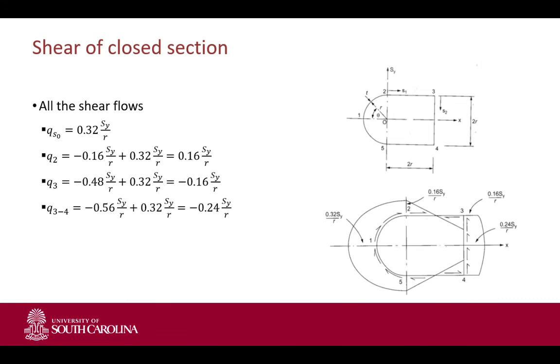And like I said earlier, the negative sign basically indicates the direction of the shear flow. So as you can see here, at one point you basically switch signs or direction of the shear flow. That doesn't represent anything else other than just the directionality. So there's no such thing as a negative shear flow. It's this definition of your directionality is in the opposite direction that you assumed.